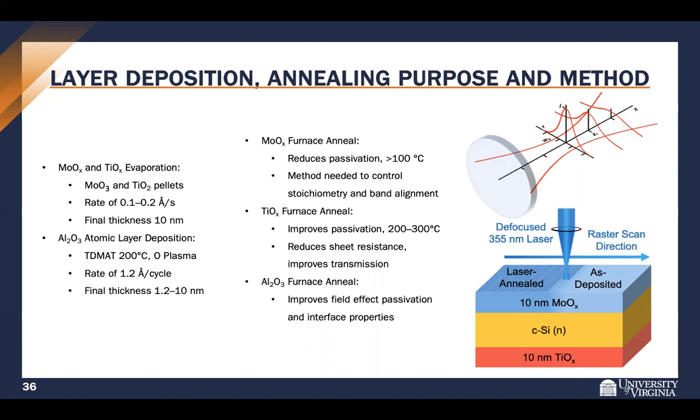So for this, I'll use a defocused laser annealing method. The beam is defocused above the sample, and this, again, spreads out the Gaussian peak to have a more uniform processing. And the beam will be raster scanned across these films to anneal them.